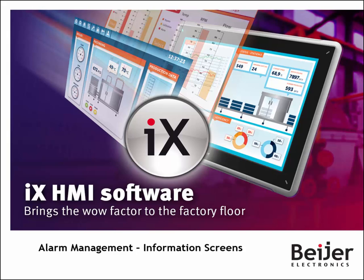This video will explain how an information screen can be connected to an alarm. The purpose of an information screen is to give the operator more detailed information about the alarm and perhaps possible solutions. This same procedure can be used to trigger any type of action, but this video will show an example of displaying a pop-up screen.